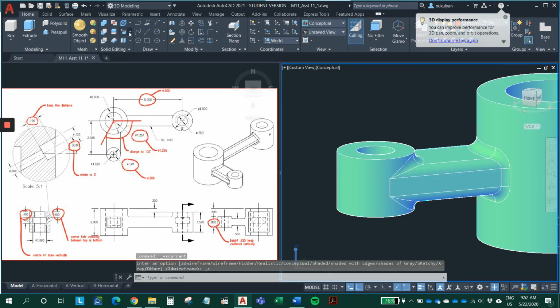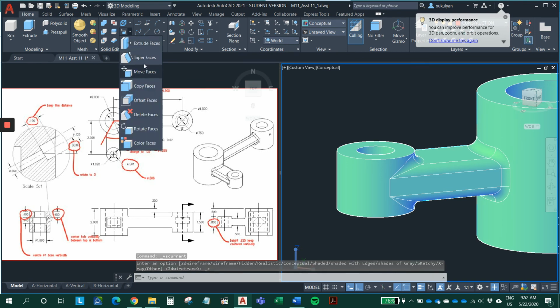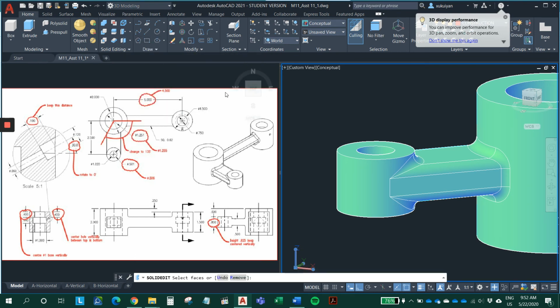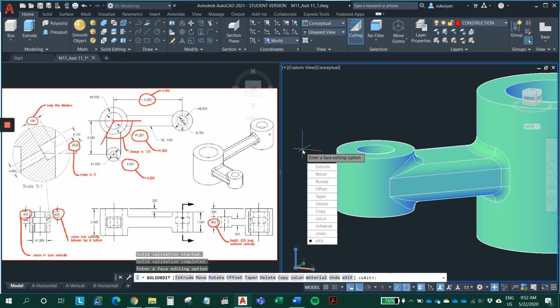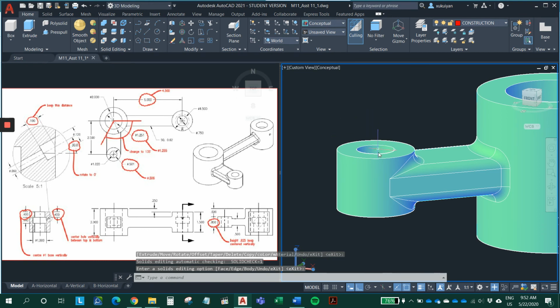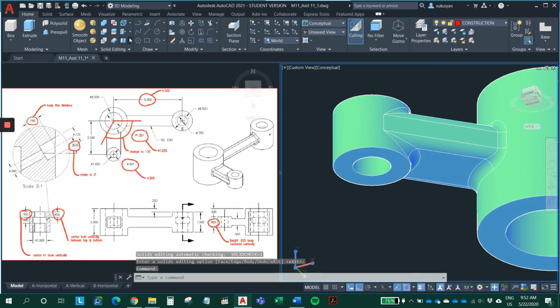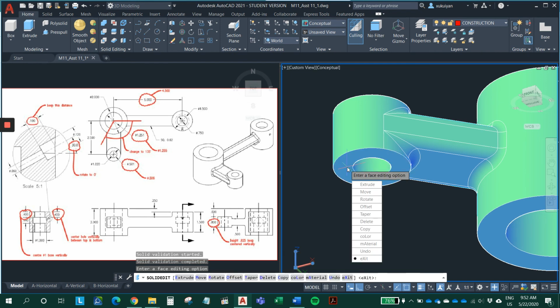So we're going to use move face again, or you can use extrude face. It's the same. So I'm going to extrude this, enter, by 0.0125. The taper angle is going to be 0. I'm going to do the same thing for the bottom face. All right. Click this, enter, 0.0125, enter, 0 angle, okay, enter.